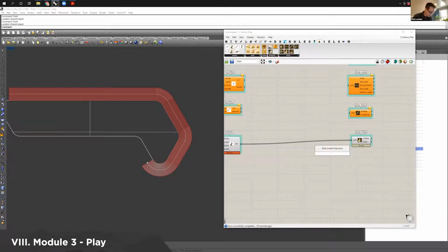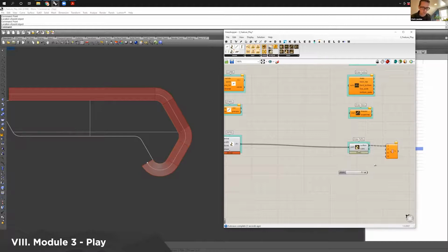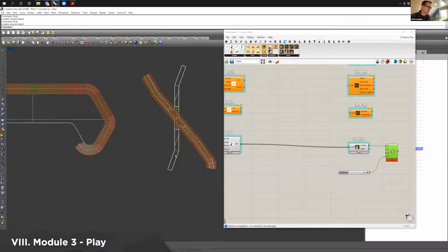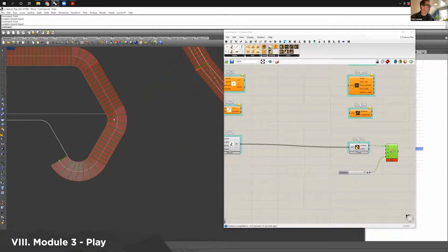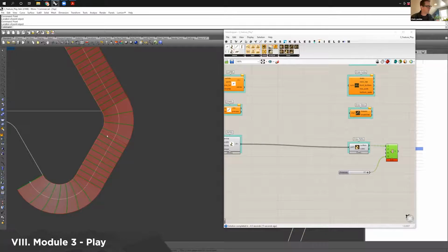I can also do a contour just to show you guys. And I'll do 1/10 of a foot, sorry. It's a fair amount of cutting. So a few interesting things happen here. If your center line is based on very simple arcs and line segments, it will grade the corner at the minimum slope, or at the slope that it needs to, so it never exceeds the 5%, right? So it's not basing it on the center line, it's actually basing it here.